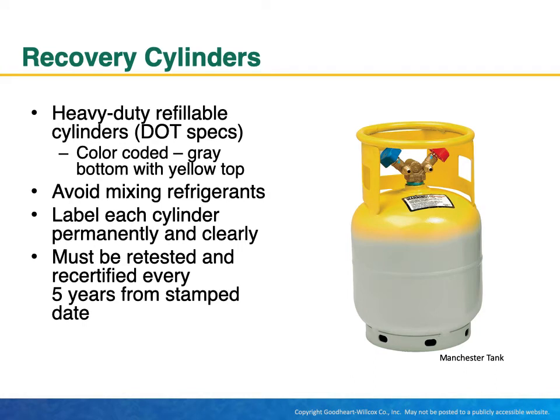Recovery cylinders. Heavy duty refillable cylinders. DOT specs. Color coded, gray bottom with yellow top. Avoid mixing refrigerants. Label each cylinder permanently and clearly. Must be retested and recertified every 5 years from stamp date.